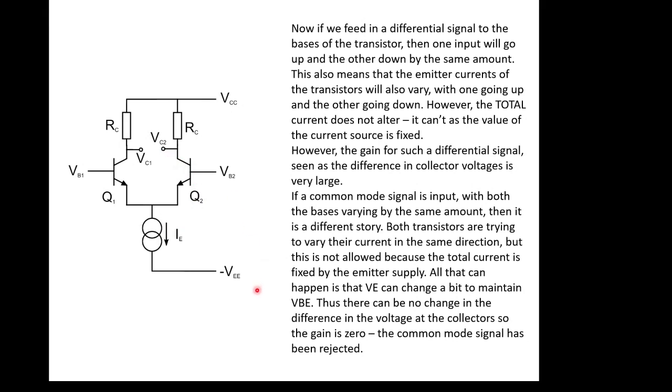And that's the only interesting one in many ways, but the difference between the two becomes really, really important. You might think, well, okay, common mode, nothing's happening, it's not amplifying anything, that's not important. It's actually really, really important, because if you think about it, most noise signals that come into the wire here will also be picked up in the wire over here as well. So you've got the same noisy signal on both sides of this system. And what happens when the same noisy signal comes in on both sides is the system goes, well, I'm not amplifying that because it's the same on both sides. So the output doesn't show the noise.